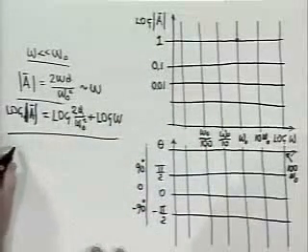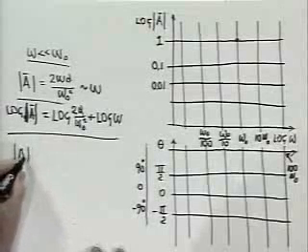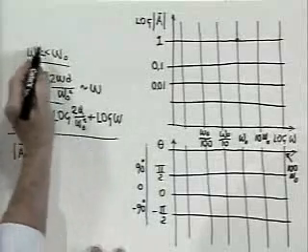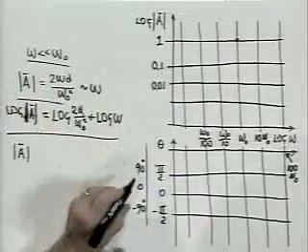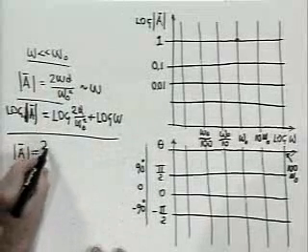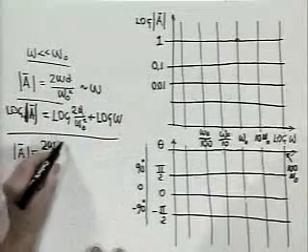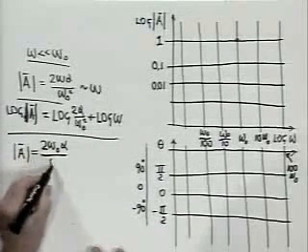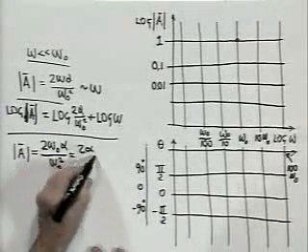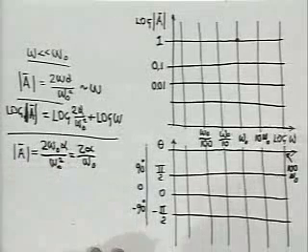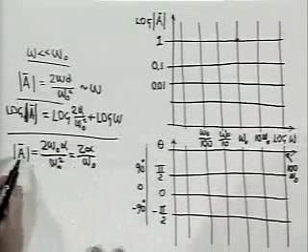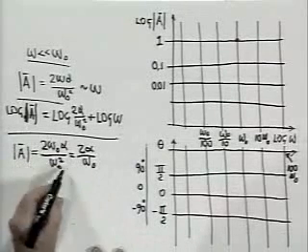Well, if we take the expression magnitude of A, which applies only as an asymptote for omega much, much less than omega naught, but find its value at omega naught, it's 2 omega naught alpha over omega naught squared, or it's 2 alpha over omega naught. That's what the value of the asymptote would be if I extended it all the way to omega naught.